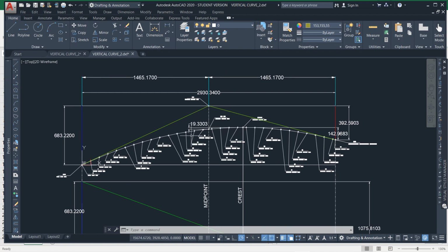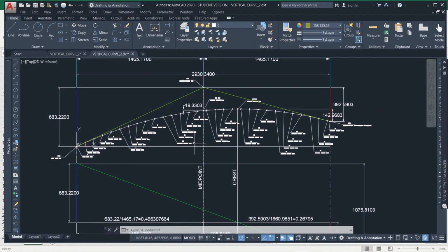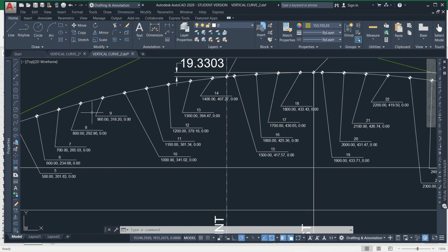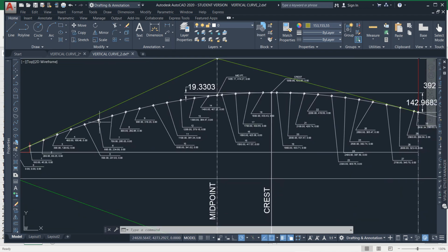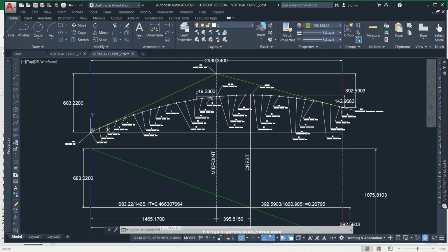Alright, welcome. In this video I'm going to try to show you what I know about vertical curve alignments. It's not much, but it could help you understand them and use them a little more easily. So in this case I've got points that are populated here along this vertical curve alignment, and they were populated using Excel, given I think we have the point 1, point of vertical curvature, point of vertical intersection, and point of vertical tangency. So you basically have the coordinates of those three.